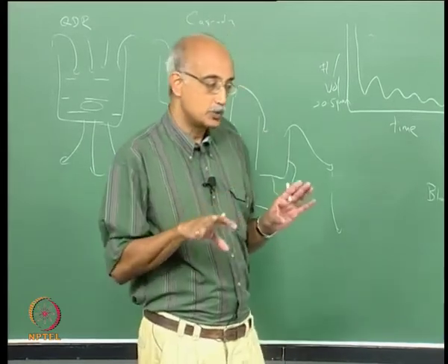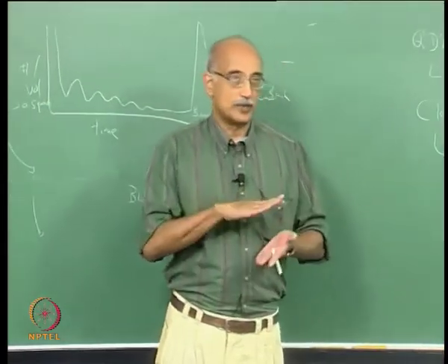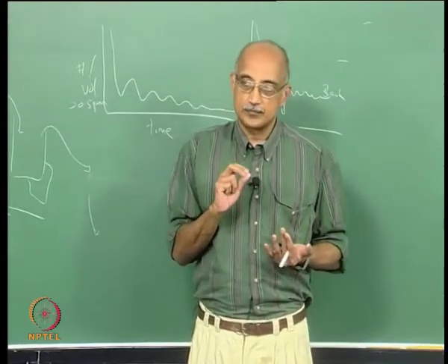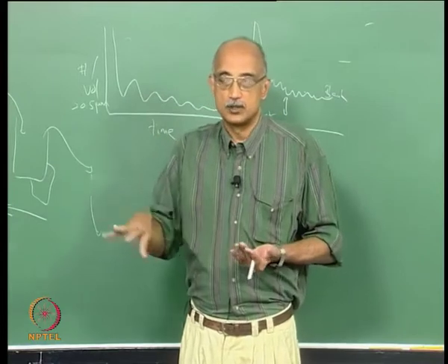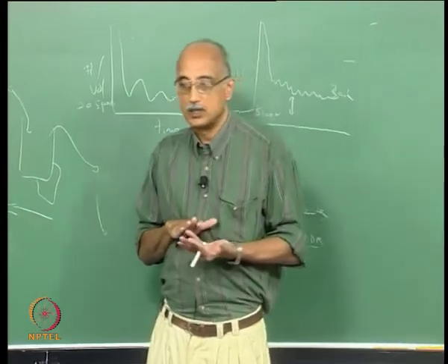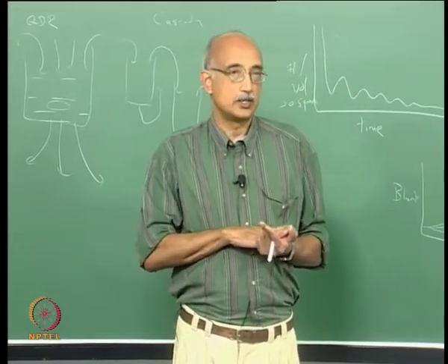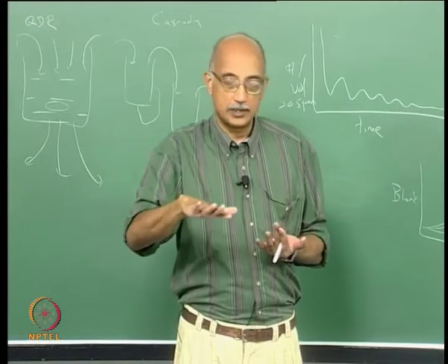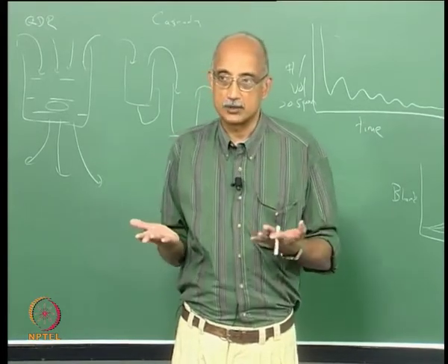The difference between the two is, in physical vapor deposition, the film that is forming on the surface is chemically the same as the material that is in the vapor phase and condensing to form the film. For example, if you are trying to form a silicon film on a surface, and you do it by essentially taking silicon vapor and causing it to condense on the substrate, that is called physical vapor deposition.